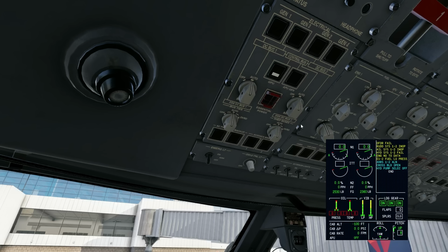Some of the equipment that's on a shed bus, for example, is the nose taxi light, some of the cabin's MP3 player or music player, and other things that are essentially things that I wouldn't be upset about losing if we happen to have a power loss, not a loss of all generators, but if, for example, we lost an engine, so now we only have half of our generators. I'll talk a little bit more about that because it has a special logic on how it works, but on ground power, the shed bus is fully energized. Once we start getting generators into play, there's a little bit more coming onto that, so we'll come back to that.